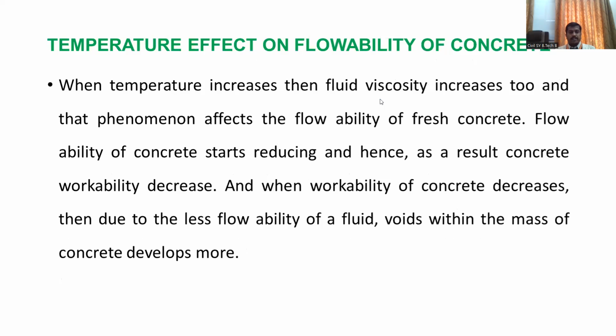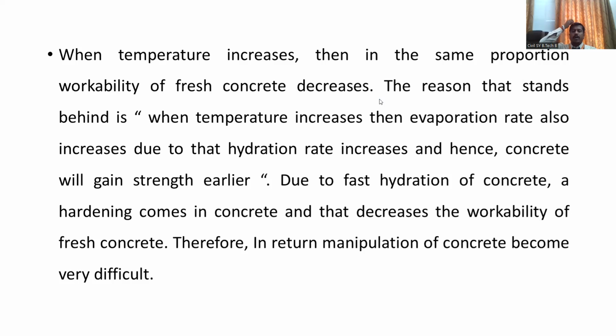So let us take the first example. Okay, that is the effect of temperature on the workability of the concrete. As I have mentioned in the PPT, as the temperature increases, there will be evaporation of the water, because your concrete is directly exposed to the environmental condition. Correct? Your concrete is exposed to the environmental condition. Okay? The temperature may be 40 degrees, 45 degrees. If there is an increase in the temperature, evaporation is also there.